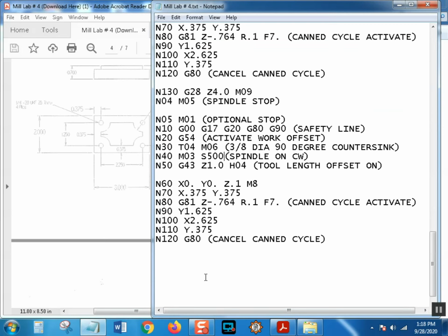You can see some of this over here. First off, you don't want to countersink that deep. With a 90-degree countersink, and we will have countersink calculations put in here, the amount you go down is equal to the amount you go over per side. So I know that I need a countersink that's a little bit bigger than 1/4 of an inch. Let's say 30 thousandths per side. That's 60 thousandths bigger. So 1/4 inch plus 60, I believe that's 310. 30 thousandths per side on 1/4 inch is pretty huge. Let's go 15 thousandths.